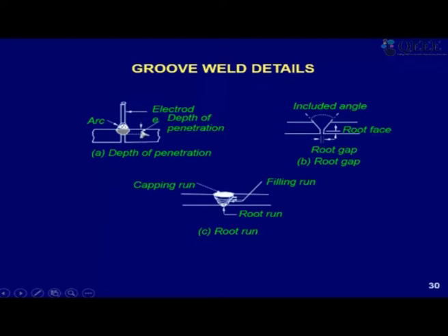So what we do is, this is called the depth of penetration of the weld. To increase this depth of penetration, otherwise I can weld only this much and this part remains unwelded, which will cause cracks, or it will not be an efficient transmission of load. So I cut a V-shaped or whatever shaped groove, and then I start welding from this. That first line of weld is called the root run. So I deposit 3 mm of metal, and then I do filling runs. Each run will deposit 3 more mm of metal.